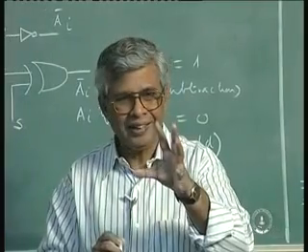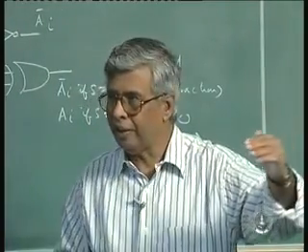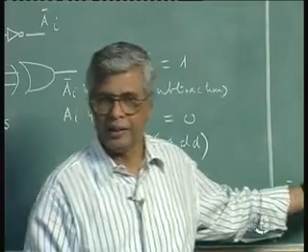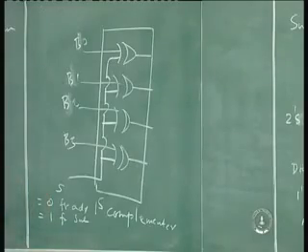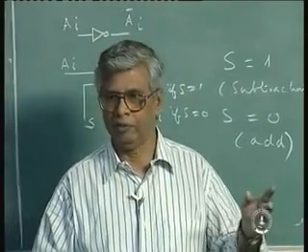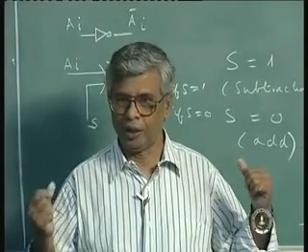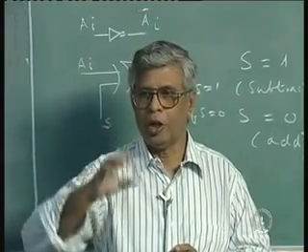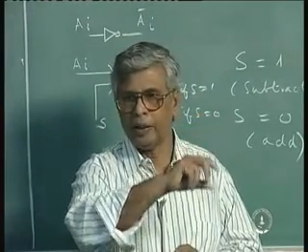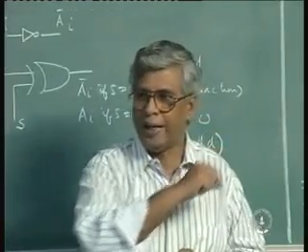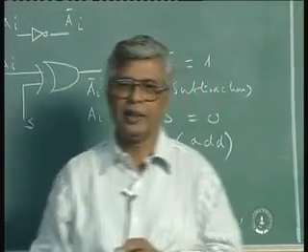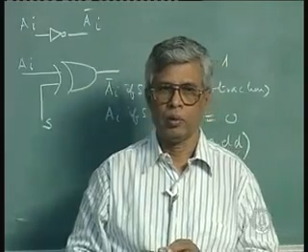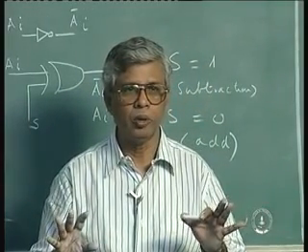So I have a full adder. A directly fed, B fed through this complementary circuitry, and connect carry in to the same S which is going to control the complementary circuitry, and then I get the output. Fair enough. Very simple. All I have to do is the drawing part of it. You can do it yourself. It's in the book. Just draw this complementer, direct input, complementary input, S controlling the complementing as well as the carry input. You get the output result as A minus B. Are there any questions? Okay.